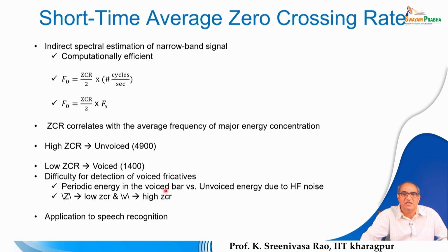So, the idea here is that, since the speech signal is a wideband signal, we pass it through a set of filters that are slightly narrow band. For example, you know that the speech frequencies range from 0 to 4 kilohertz.